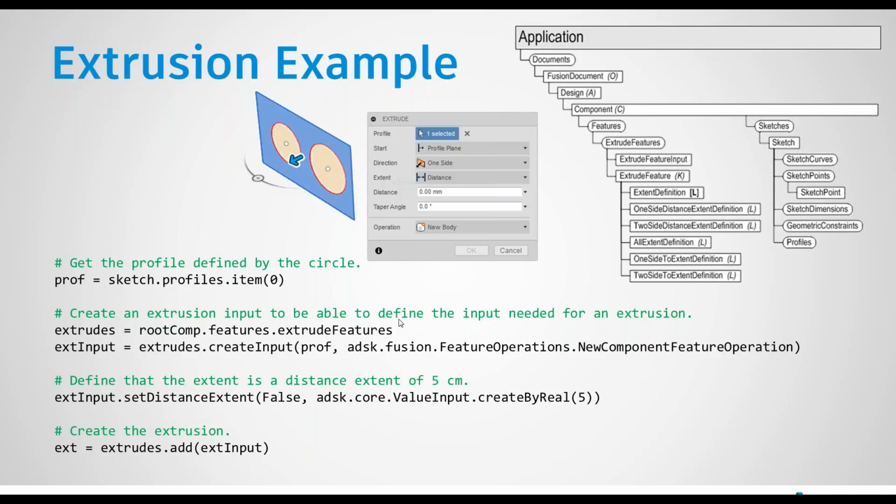And now from that sketch, in the user interface, when I draw a sketch and then run a command, here the extrude command, as I move the mouse over the model, different portions of that sketch will highlight. And those are referred to as profiles. So they're closed areas within the sketch that Fusion has computed.